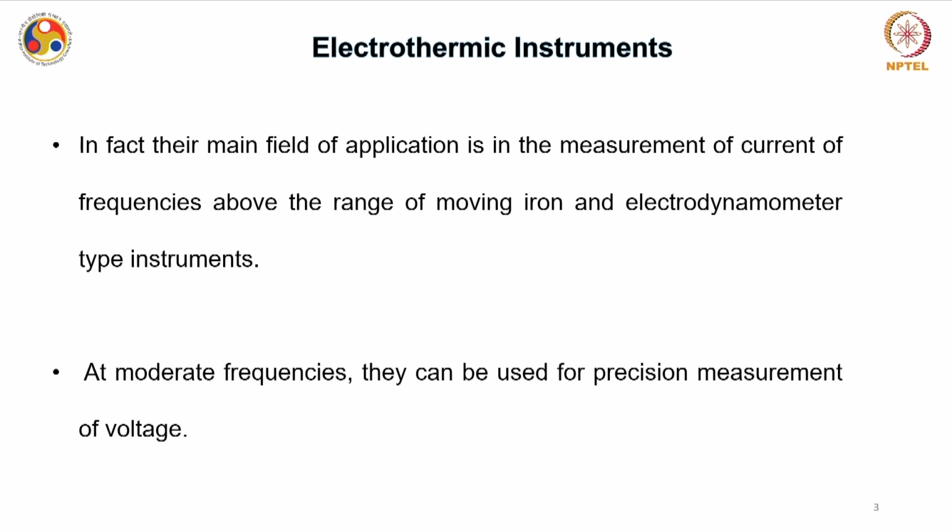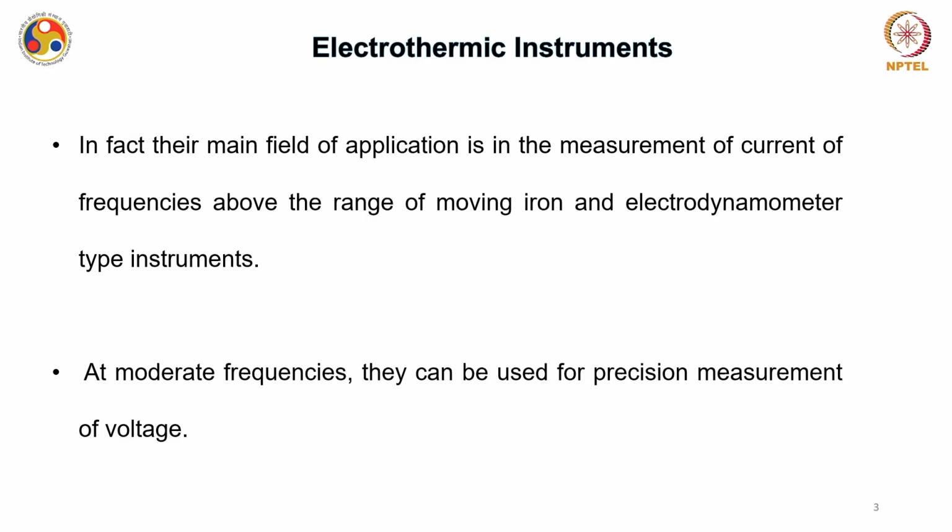In fact, their main field of application is the measurement of current at frequencies above the range of the other instruments that we have already covered, like the moving iron instrument, or the transfer instrument that we have seen, the electrodynamometer type of instrument. At moderate frequencies, they can be used for very precise measurement of current or voltages.